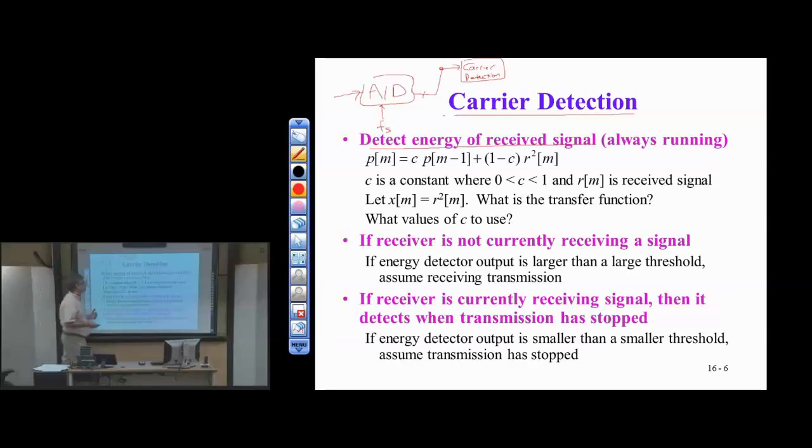Consider the running summation all the way back to homeworks 1 and 2. Remember, the fast implementation for running summation was that its output is just the previous output plus the current input value, right? That was the fast way to do running summation. But as you just pointed out, this is not BIBO stable.